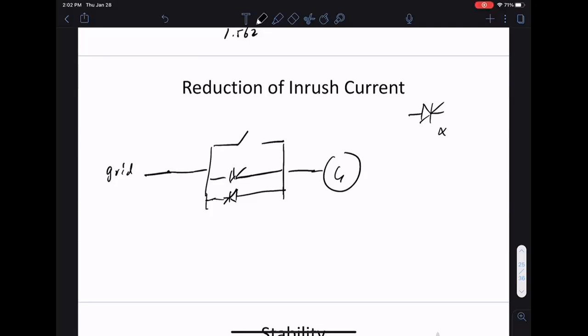As you build this kind of protection, you build this kind of circuit around it. By varying the triggering angle, you can set the upper limit of the rush of current through the system. And these are power electronic devices, because they have to stop a lot of current, so they're bulky, big devices. So that's one thing we care about.